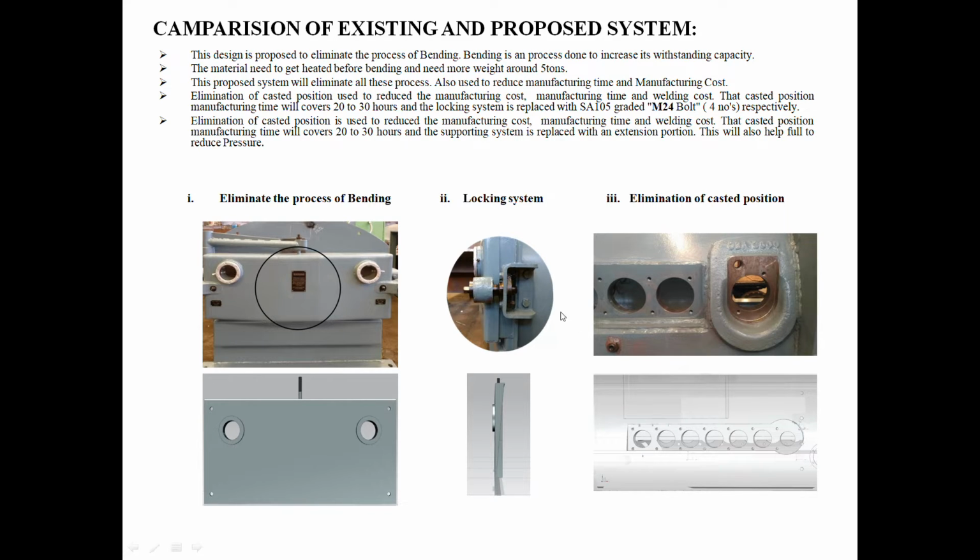At last, locking. The inspection door is locked with a huge lug, which weighs around 40 kgs each. So we wanted to search for a new design where the system is hinged with bolts and the locking lugs are eliminated.